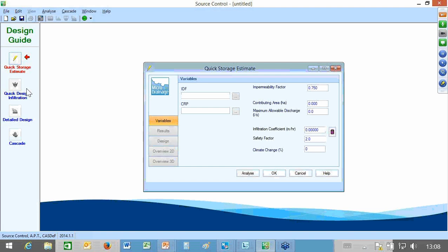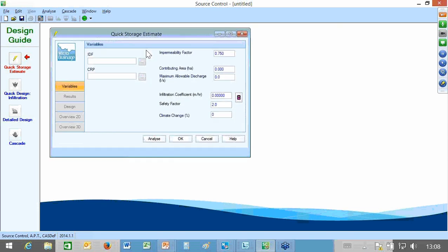So first step, let's look at how much volume of storage we would need under the ground to make sure there is no flooding for the 50-year event for this particular site. And this leads us straight into the rainfall criteria. Now, after the first and the second webinars, there were a lot of questions about how do we generate rainfall profiles, how do we set up the characteristics for our particular country, and this is the how-do-I bit of the rainfall that I'm going to show you now.